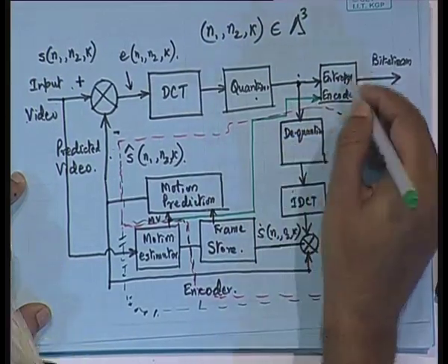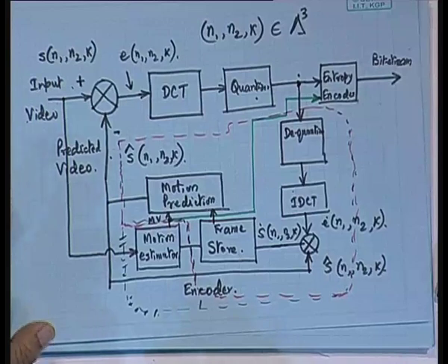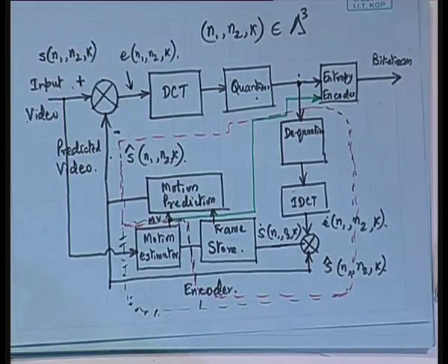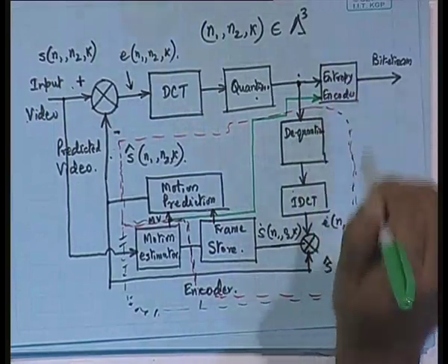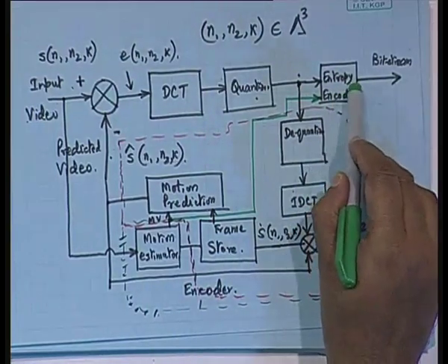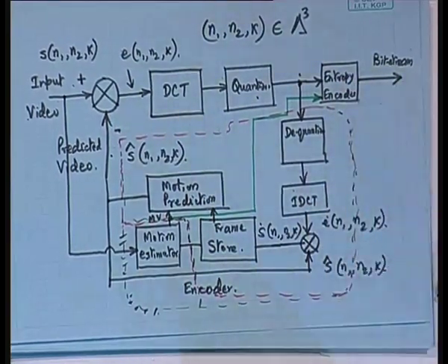into this place, where the motion vectors will have some similarities between themselves. That means the motion vector of one block and the motion vectors of the neighboring blocks are going to have some kind of similarity, so you can exploit that in the entropy encoding process. The motion vectors can go through the entropy encoding scheme and into the bit stream.